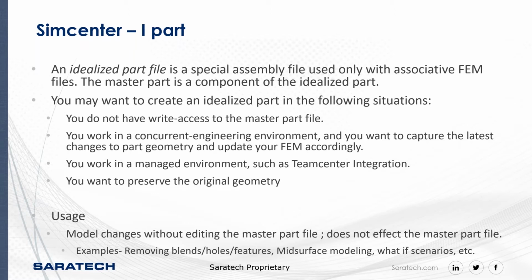You don't have write access to the master part. You're working in a concurrent engineering environment. So say I'm working with somebody else on the same part, and I bring in my local part that I want to do CAE analysis on, and maybe I want to ignore a round, a fillet, a hole. I don't want to go ahead and delete that from the model and have it affect his model. So I create my own local copy that's associative to his, but when I make changes, I do not update the master part. Now, I can have my localized copy update to the master part. If the designers, whoever's working on that part, make a change, it will propagate automatically into my part. And I'll show that in a demonstration.